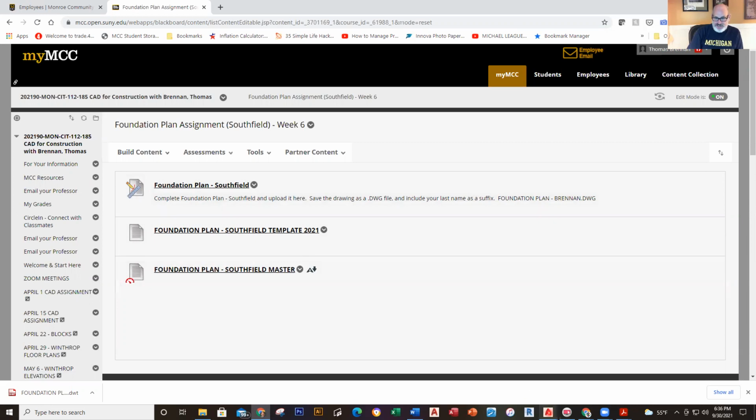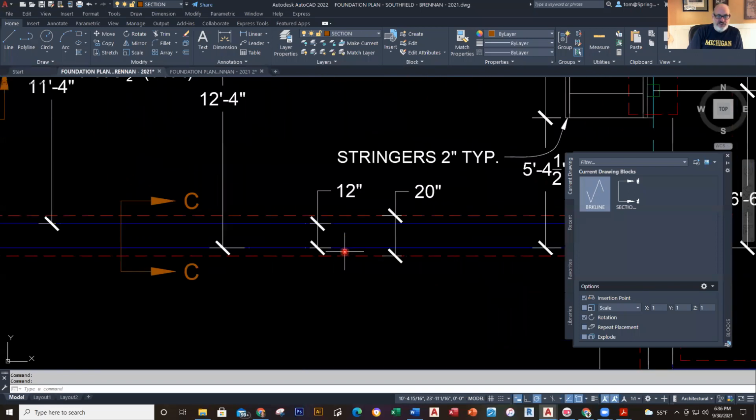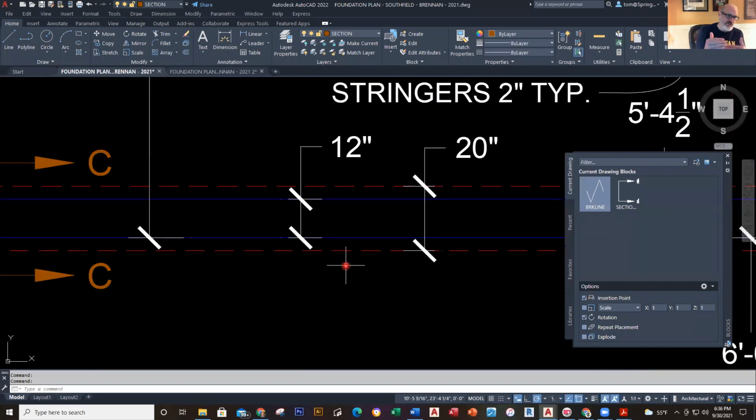Okay, so getting back to here, let's think about this wall now. So you got a 12-inch wall. Let's just imagine that's a poured concrete wall, or it might be concrete masonry unit, CMU. When we talk about CMU, what we're talking about is what used to be called cinder blocks. They're concrete blocks, okay? And concrete blocks are actually hollow on the inside. They have 2 hollow compartments, and then they get stacked, and mortar goes between them to stack them up.